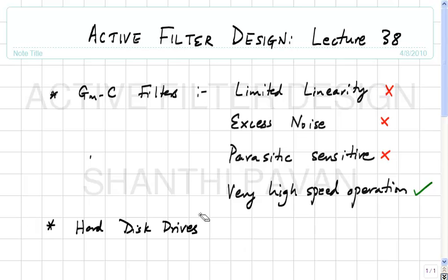Another thing is that you also want to maintain the same characteristics. The shape of the response must remain the same whether you are at the inner diameter or the outer diameter, correct, because everything in the channel remains the same. It's just that time has been stretched, that's all. So the rate at which you sample in the AD converter will reduce at the inner diameter, the filter bandwidth will reduce, right, and so on and so on.